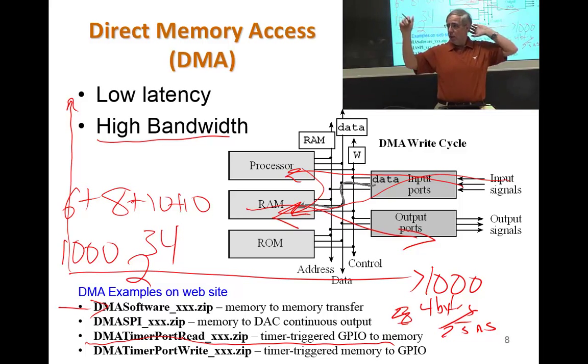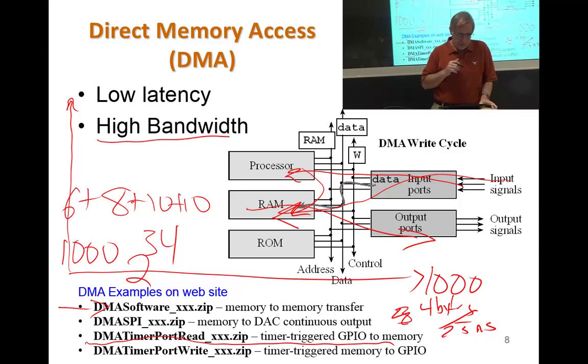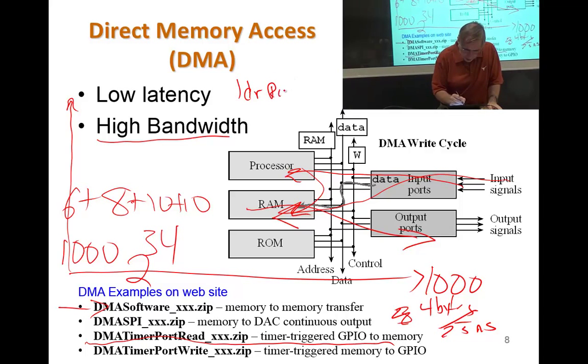Questions? Isn't this the same thing as memory mapped I/O? No, there's no software executing. Software, he said, is the same as memory mapped I/O. No, because if I were to stream data from memory, right, I'd have to do something like this: load R, R0, R1 plus, right, and then I'd have to do store R, R0, R2 plus, right?